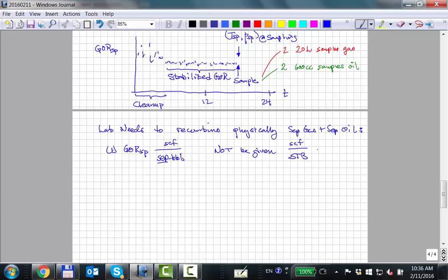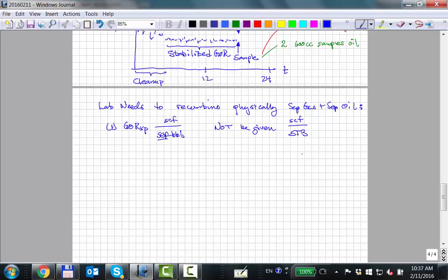And if the testing company reports the oil volumes as stock tank barrels, you have to figure out what was the separator barrel. Okay? Nobody else but you. And if you don't do it right, you've screwed up. You didn't sit in my class. Okay? So if the testing company, and they do sometimes do this, sometimes they report stock tank oil volumes. Sometimes they just write barrels and you don't know. So you have to ask.